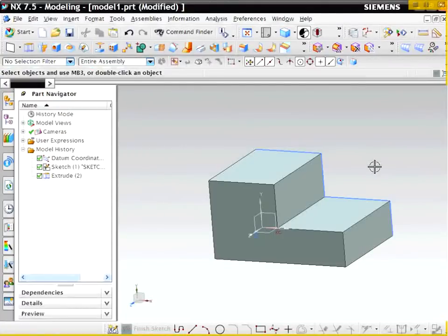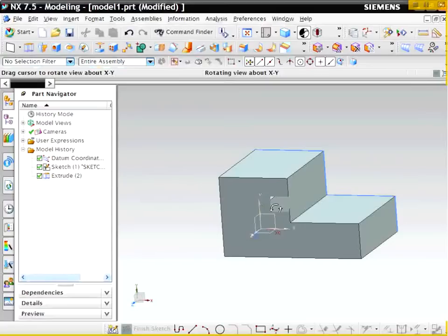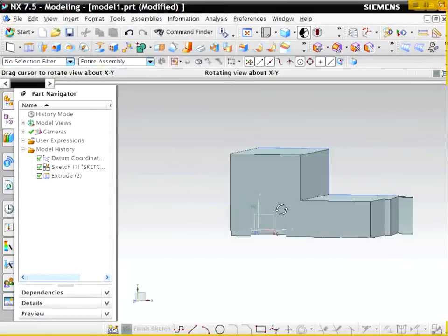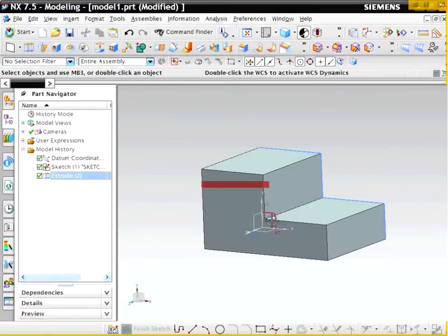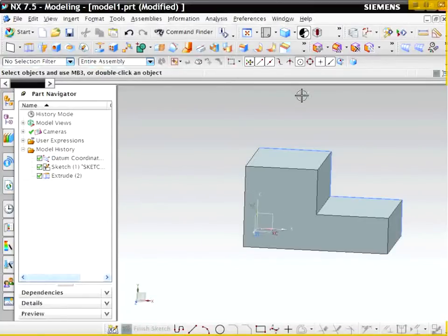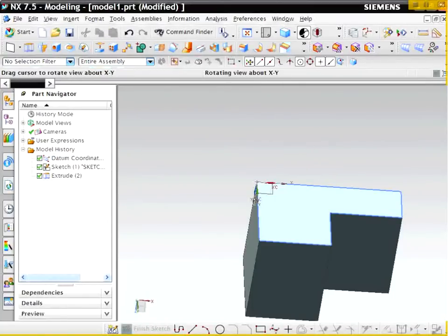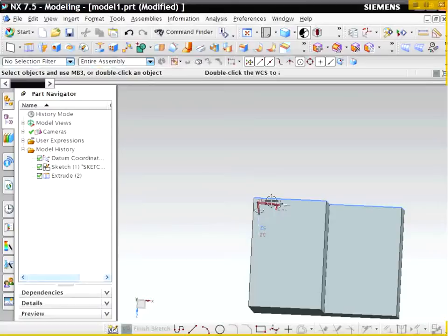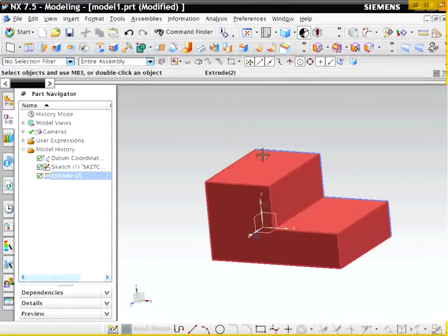Now I'm going to use this shape to illustrate what we're going to call the datum plane or datum axis. You saw that when we started the sketch, we used our traditional XY coordinate plane. I'm highlighting it here, and you can see it in a pinkish color. This plane is what we used. What happens if I want to draw something up here facing down this way? Well, I can use the XZ coordinate plane, but I may want to do it in reference to another plane on this object.